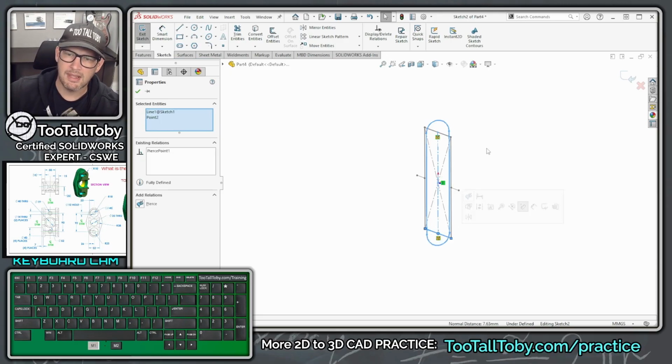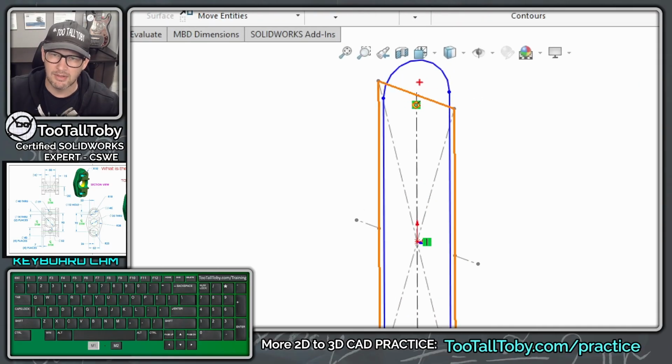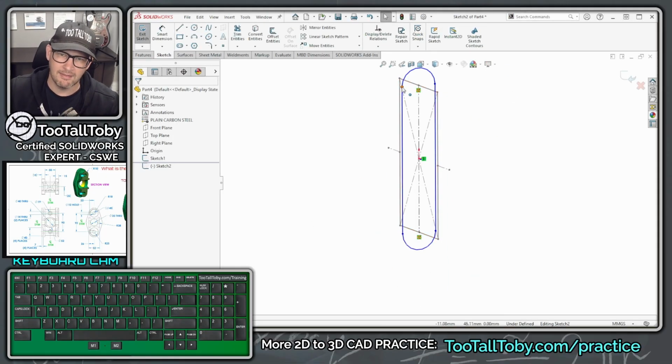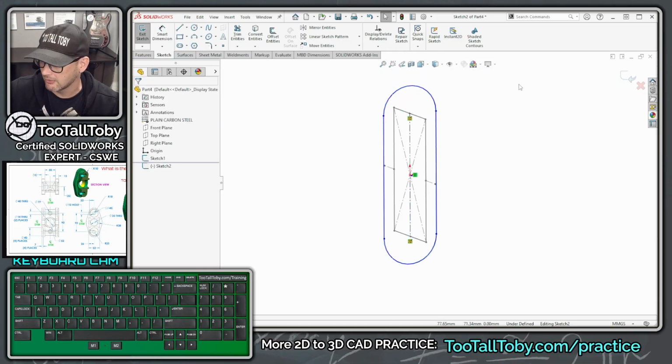And of course, I've got a video on pierce as well if you want to learn more about that. But basically what I'm doing is I'm saying I want this point in the sketch to exist where this line passes through the sketch. That's how pierce works. And in the case of using a layout, that's very helpful because now I know that that distance is going to be 92 millimeters from that first sketch, 92 millimeters.